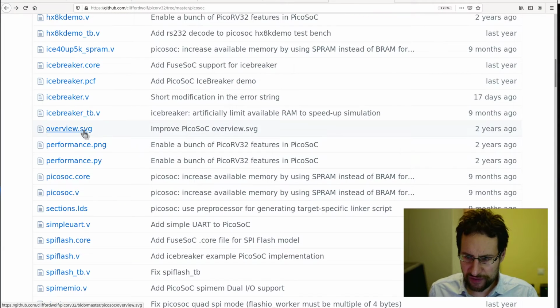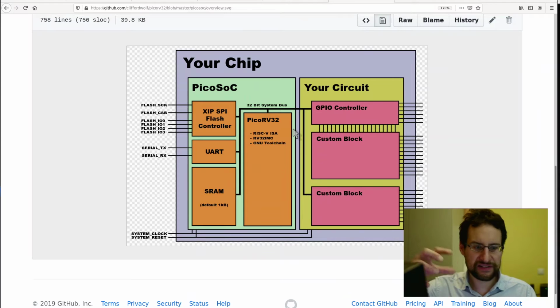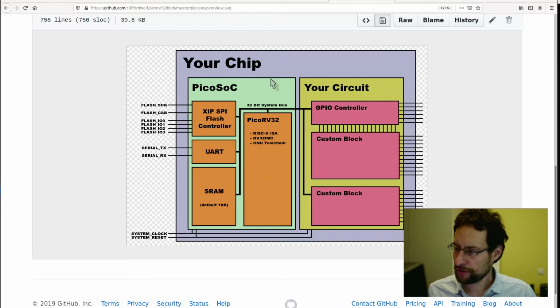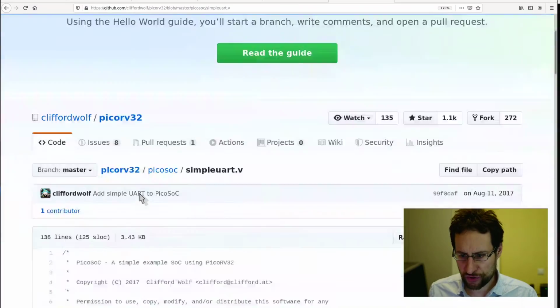The next challenge will be placing this here on the bus. Even if this would work to synthesize, adding this to the Verilog code, to the makefile, synthesizing this with Yosys, it would not be connected. So we would also need to write our bus interface glue logic code to interface with this 32-bit system bus. Probably similar to, let's see how the simple UART is doing this.